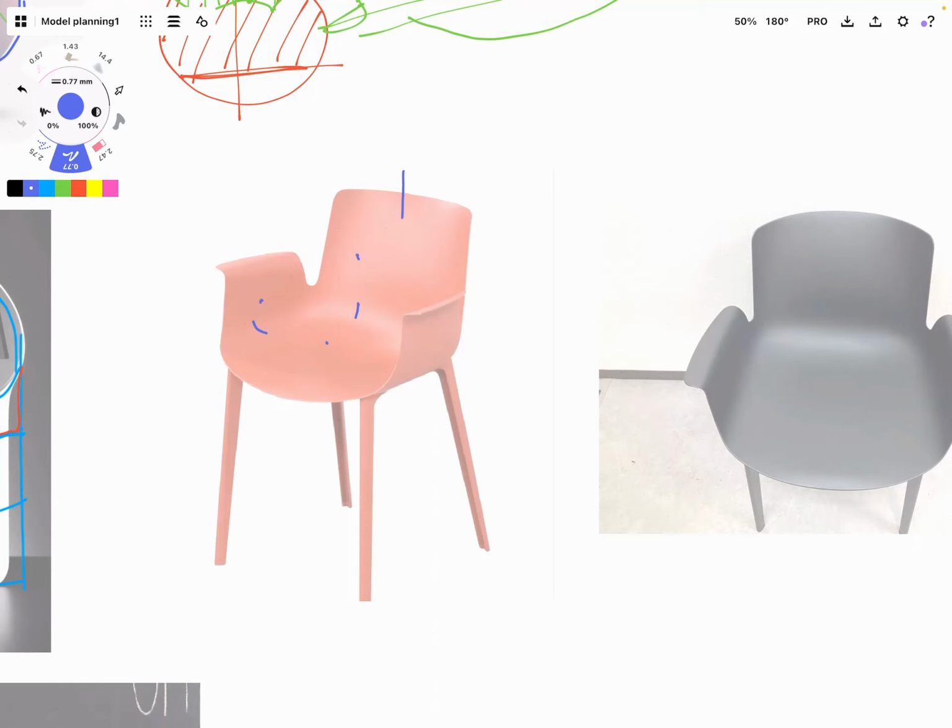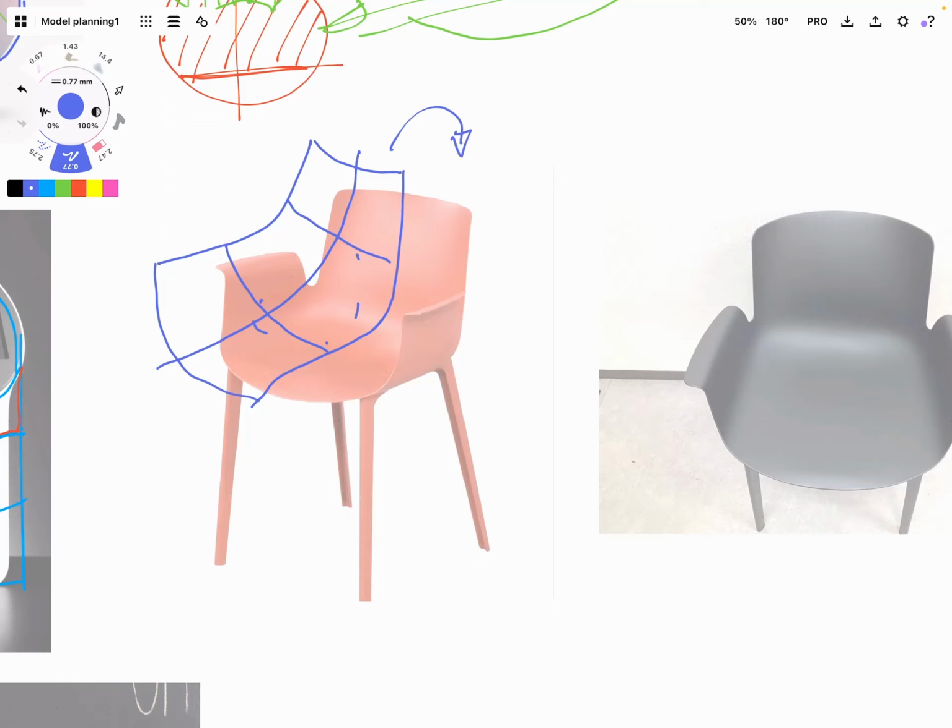You'd figure out maybe the center line, and because it's an overbuilt surface you need to make it four-sided, and then you have another boundary, you have another boundary, and then you have another boundary, and then you end up invariably with several cross curves to control the form, and then you mirror that over, or you build it all full width like so, which means you don't end up with any curvature issues along the center line.